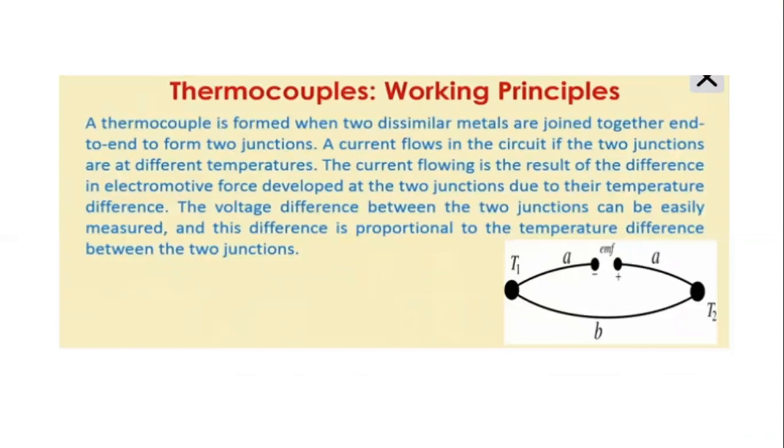So thermocouple, I will explain the thermocouple working principle. Mainly it is constructed by using two metallic wires, but they are different metals. So a thermoelectric sensor or thermocouple is a temperature transducer that develops an EMF, which is a function of temperature between a hot junction and a cold junction. Here you can see a thermocouple. It can be constructed by using two wires. You can see wire A and wire B.